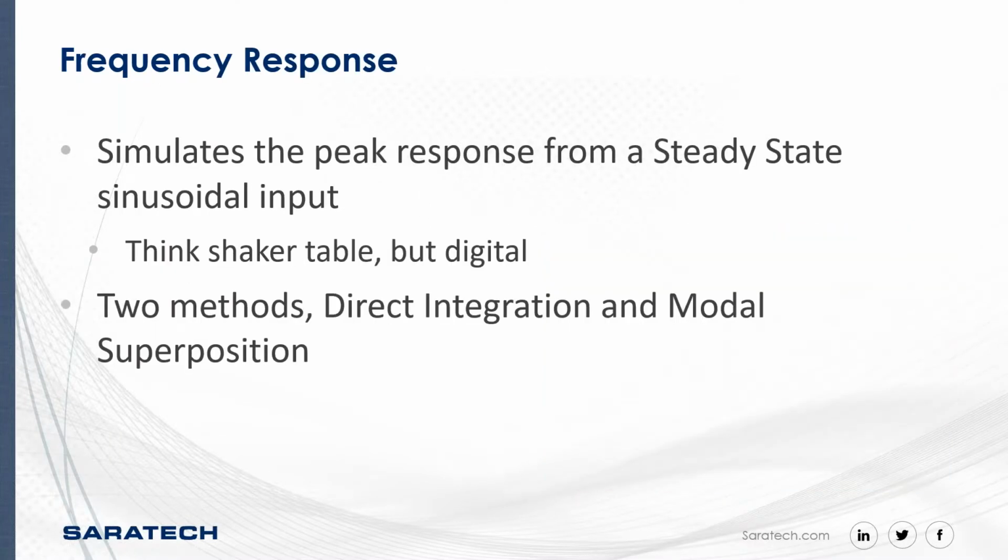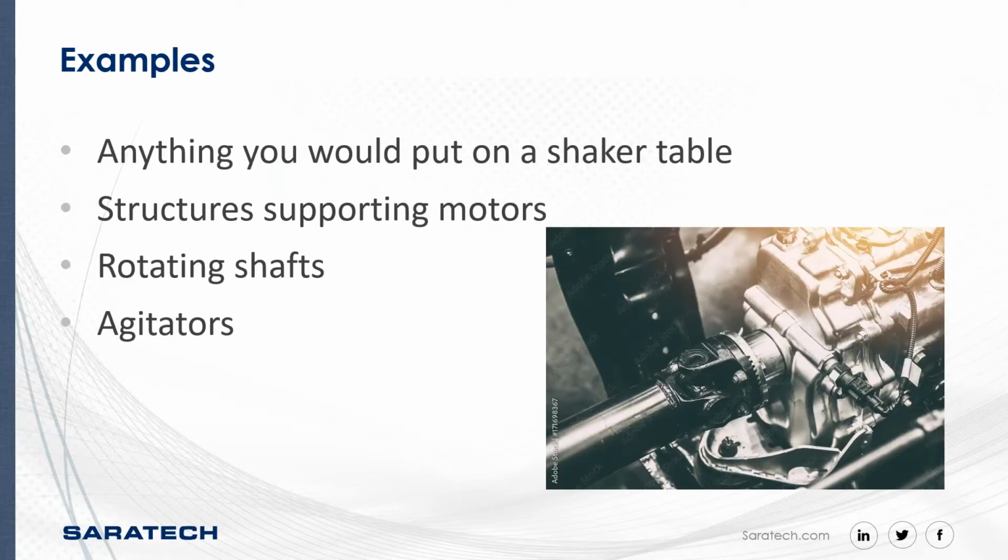So frequency response is the simulation of the peak response from a steady state sinusoidal input. The easiest way to describe this is to think of a shaker table, but digital. It does exactly what a shaker table does for the most part. There are two methods, direct integration and modal superposition, but we'll talk about those differences later on.